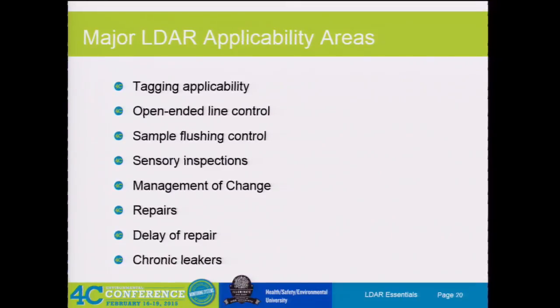You guys have all had out of service components. How many folks have had operations tell you it's out of service, but when you find out it was actually not LDAR out of service? So you guys didn't purge the material. It still had something, it's just not in operations right now, but it still has product in the pipe. Well, is that still LDAR applicable?